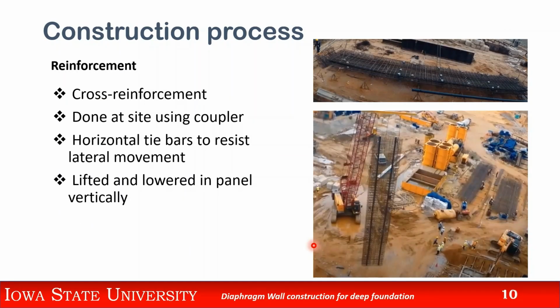After you have the slurry done, you want to do the reinforcement installation. So the reinforcement is made or assembled on the site itself, where you can see I have longitudinal bars and lateral bars. This is done normally to resist the longitudinal and lateral pressure. And as you can see in the center, these hollow pipes, this is the pipe you can see here as well.